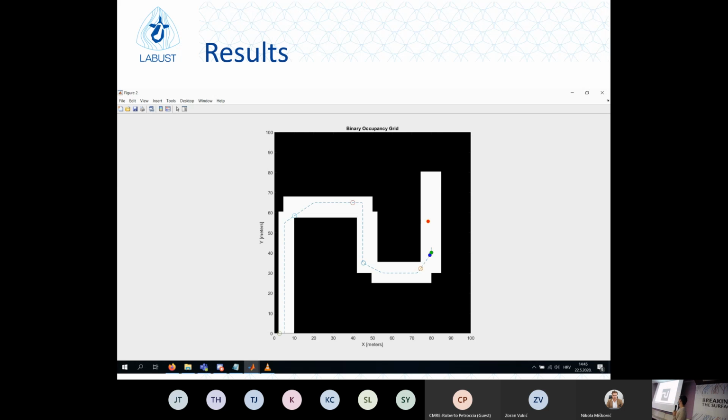And as you're going to see here, right at the end, we have a slight drift because this observability was not that great. You're going to have a slight drift, but when the beacon comes back down, as is the intention with this breadcrumb algorithm, it binds the error right back on the track because observability is much better.